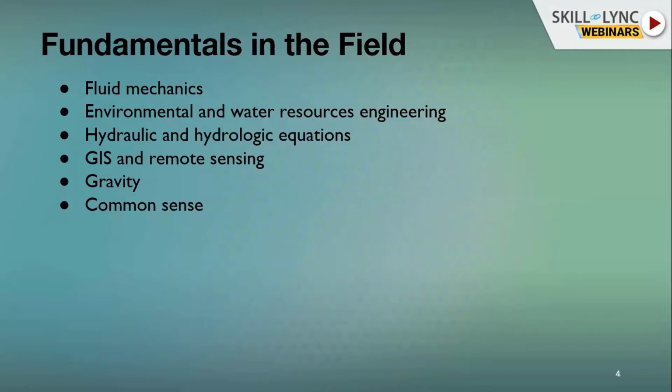Then people should really understand hydrology, because it's hydrology first and then hydraulics second. People should know what runoff is. Runoff is equal to rainfall minus losses, and rainfall is straightforward, that is the precipitation, and losses are nothing but your evaporation, evapotranspiration, and infiltration losses that you usually study in your water resources engineering. This is nothing but open channel hydraulics. I would also suggest that people should know what an open channel is, the things which I described earlier.